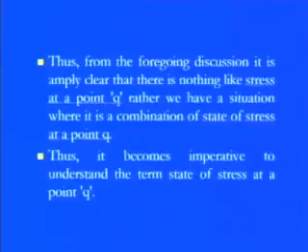We have to be very careful, because if you want to design something, once the impact is there or even the regular forces are there, we have to be very careful about what has happened inside the object, whether only the stresses are there, or whether the internal resistive forces can sustain these impactive forces or the regular forces. So rather than discussing a simple stress at a point Q, we should discuss the combination of the state of stresses, or we can say the generalized state of stress at a particular point. It is the combination of various stresses. Thus it becomes imperative to understand the term state of stress at a point Q.